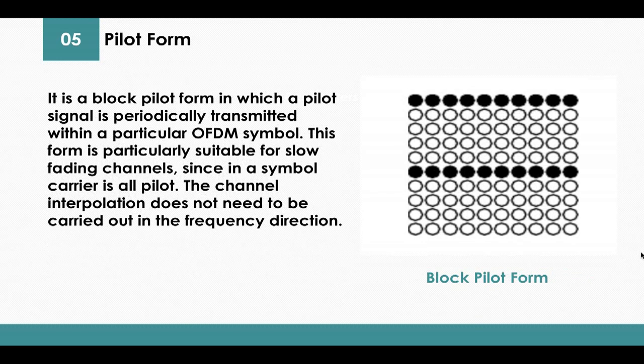And this is the block pilot form, in which a pilot signal is periodically transmitted within a particular OFDM symbol. This form is particularly suitable for slow-fading channels since the symbol carries all pilots.